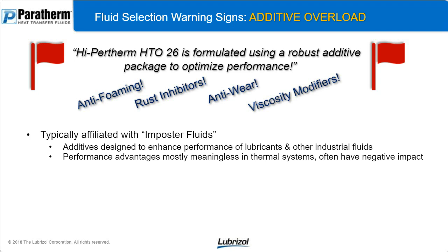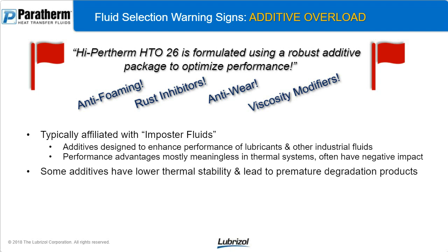Okay. Some additives actually have some benefit. Most additives have a much lower thermal stability than the actual oil that they're being added to. The base chemistry of the fluid should be what's robust, not the additive package that you add to it. Because what'll happen is the add pack that goes into that, whatever those additives are, that aren't helping you transfer better heat, are going to end up fouling out of solution, fouling out of the fluid, onto the equipment surfaces, into the solid form, plugging lines, causing all kinds of nightmares and the downward spiral that we're looking for. So don't choose a fluid that already has those things in it. They're just as bad sometimes as the actual impurities from an impurified fluid.